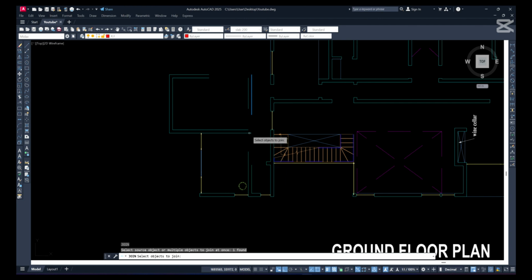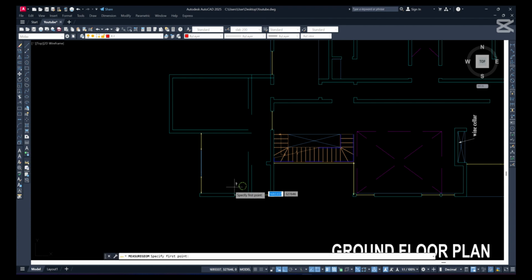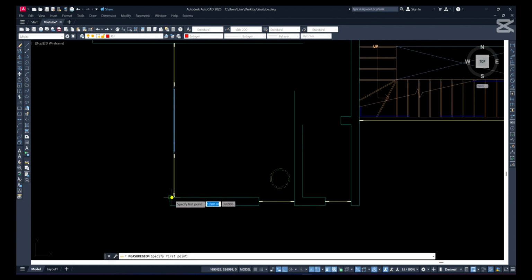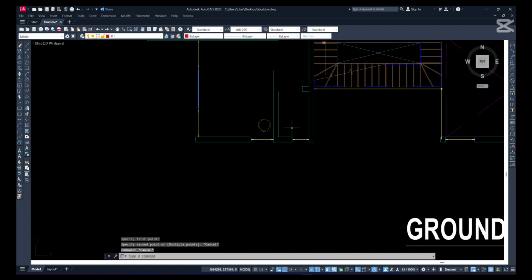Like areas where we have toilet partitions, I took them off and made them just one panel. I prefer to have my designs having fewer beams, more panels. More beams, more costs. And sometimes more beams requires more columns. So everything still boils down to the structural engineer's risk appetite and level of experience too.